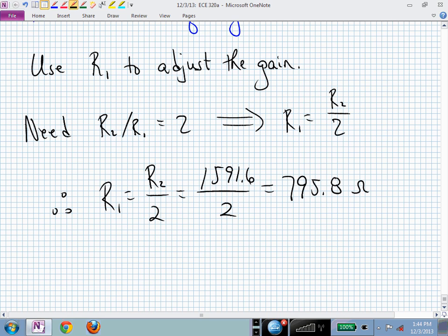Other questions on this? Yes. So the question was, it looks like it would be okay with the low pass and the high pass because you really just have this one frequency to worry about. Now with respect to a band pass, you have to worry not only about the center of that band pass, but also its width. And that's the Q that was referred to earlier. You need to worry about the Q.